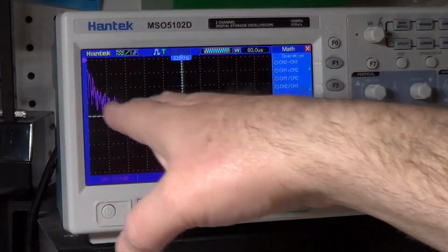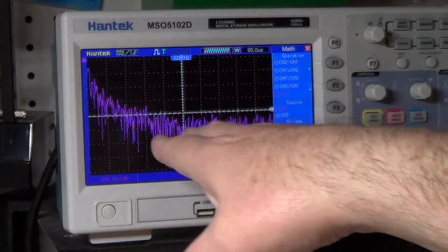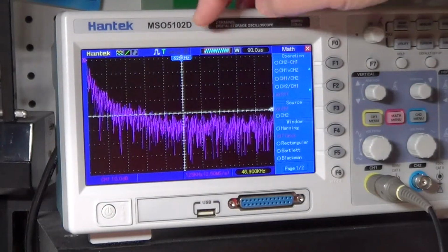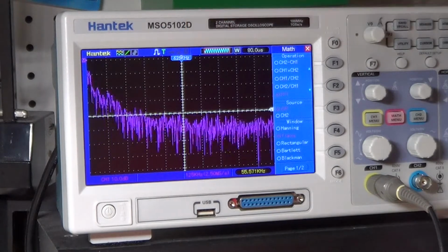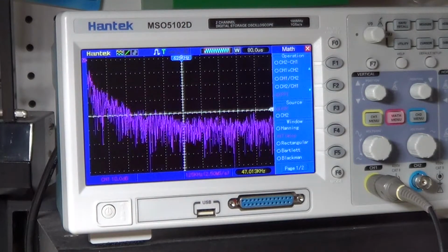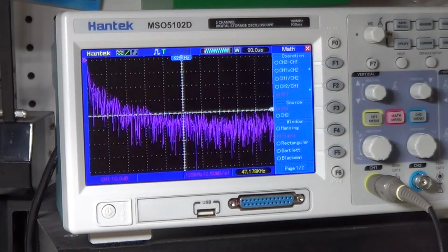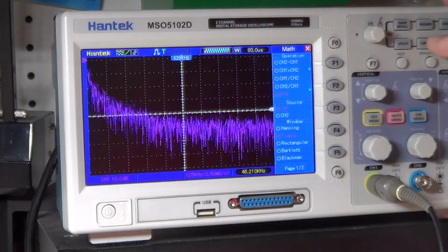You see now there is this interval here where it basically changed the way we want it. We are far away from the cutoff frequency now, so we now can make reasonable measurements about the attenuation slope. Let's turn on the cursors.